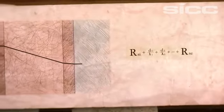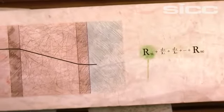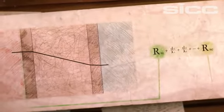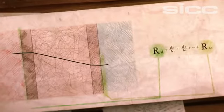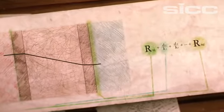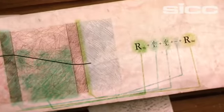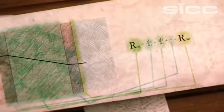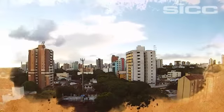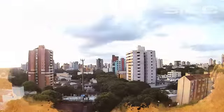This heat transfer coefficient of the wall is built up by the resistance of both inside and outside. Of course, they are DIN standardized, and they are marked as steady. The wall consists of independent layers of construction material which are specified by their thickness and value of heat conduction. For most buildings without insulation, U-values of 1.2 are known.